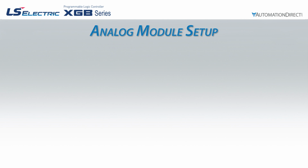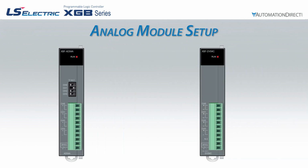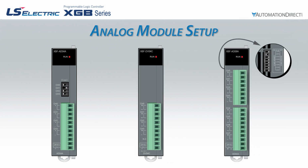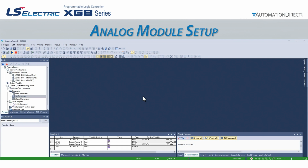The first step for configuration is to determine if our module has a physical selector switch to select voltage or current. Some models do, and others do not. Some switches are located on the front face of the module, and other switches are located on the side and will not be visible or adjustable when the PLC rack is assembled and powered up. Please refer to the documentation for your module to find out if it has switches and what each switch position means. Once we have set the switches, if there are any, to the correct signal type for our application, we can work on the software configuration.